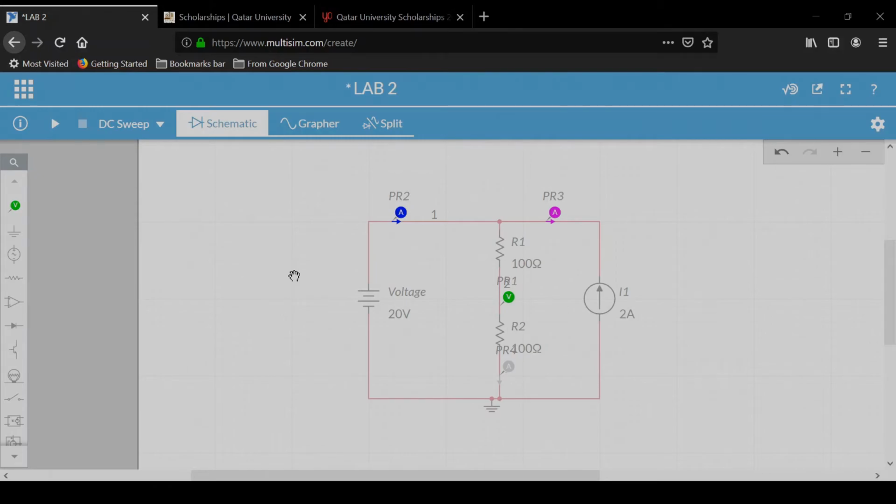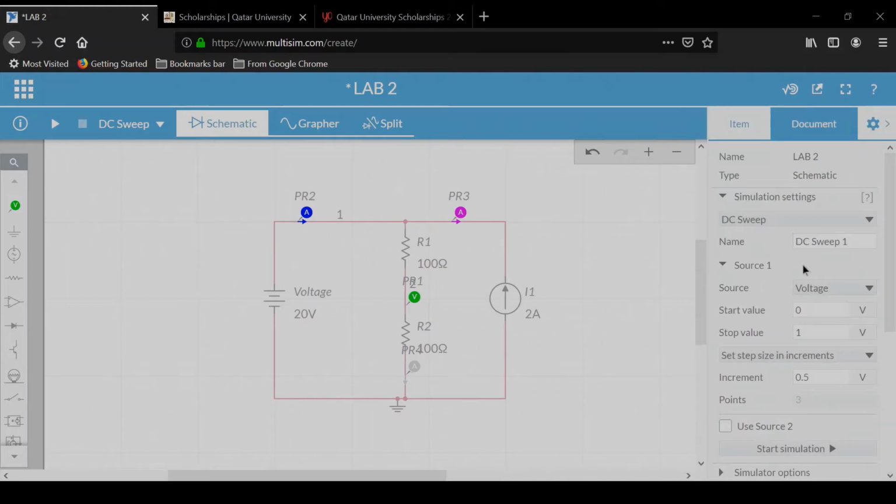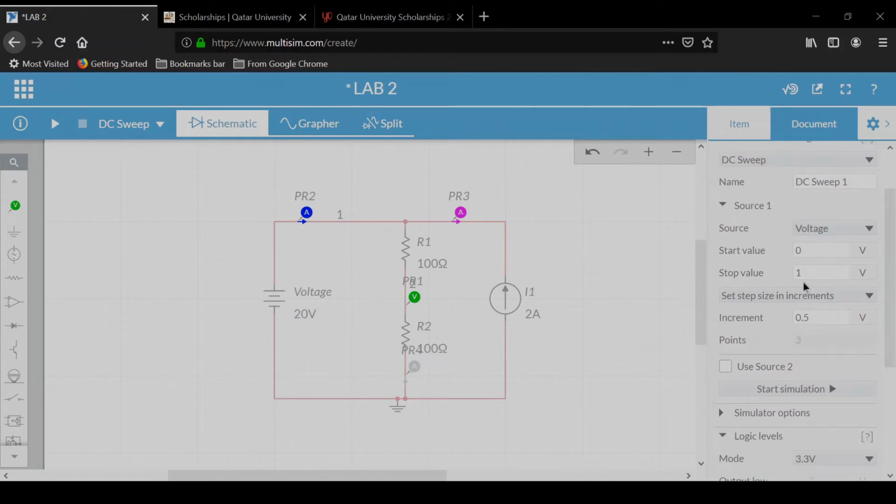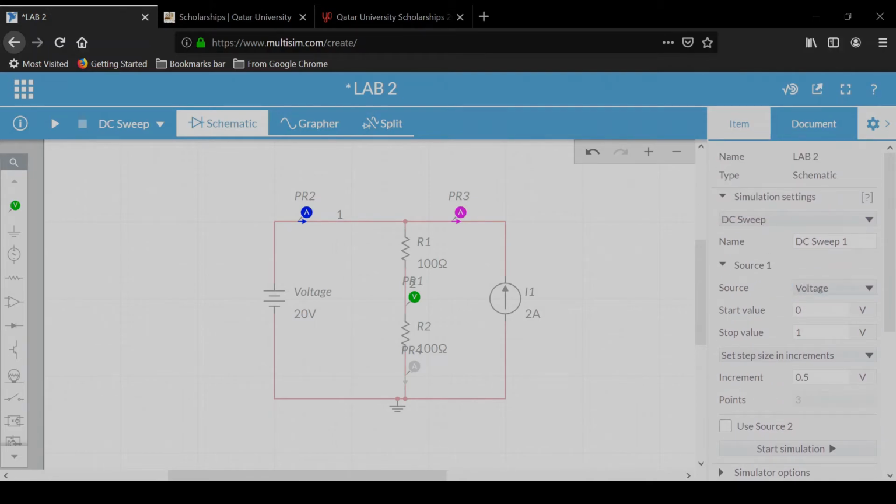Now we need to go to the simulation settings to change the sweep parameters. What sweeping is is implied in its name. What we want to do is to see the effect of different voltages at a specific increment. Let's make that a 1 volt interval from -10V up to 10V.